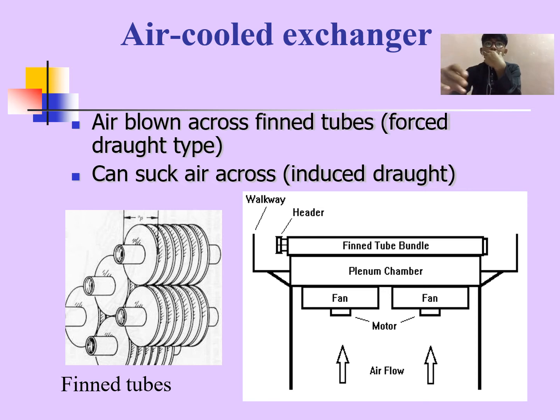The advantage of cooling with air can be seen by comparing air cooling with alternative cooling with water. This issue should be reviewed on a case-by-case basis to assess whether the air cooled system is economical and practical for the intended application. The main components of an air-cooled heat exchanger include the fin tube bundles, fan and drive assembly, air plenum chamber, and overall structure installation.